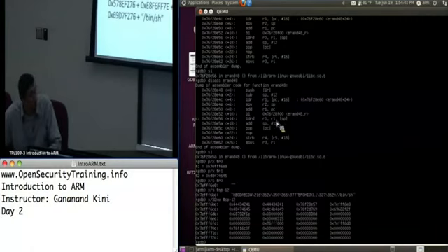load the address of the string into R0, and then you'll get the junk value, which in my case I use like EFGH. And then I add another junk value because the stack pointer is being decremented by 3 stack spaces instead of just 2. So you'll have R0, which is the address of your string, R1, and then one more value. So I used EFGH, IJKL as the junk values so that the stack pointer would adjust itself.